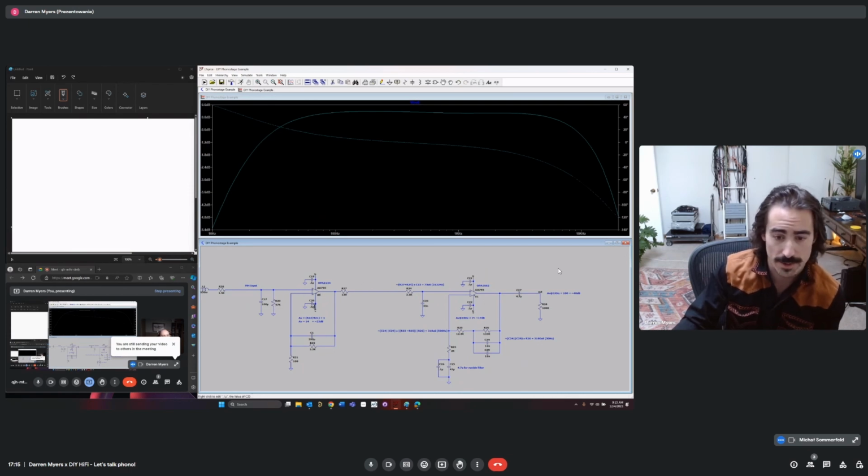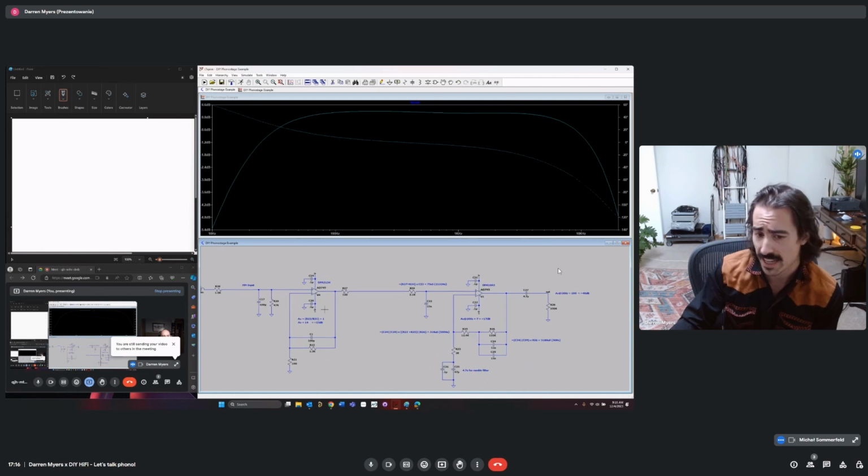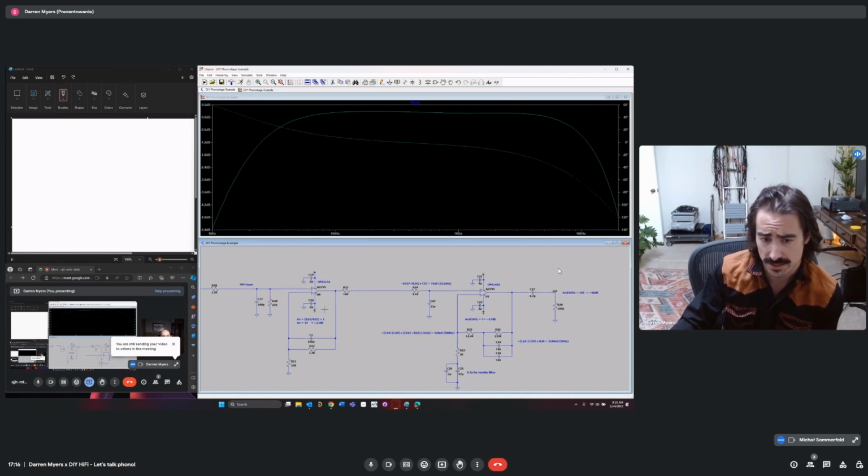If you had some op-amp that had a horrible DC specification, you're just going to get more offset right here. We have blocked this, but you would still get roughly 14 times more offset on the output here than the input. And that's not very desirable. So we want an op-amp that has a great DC specification, considering that it also has great noise performance.